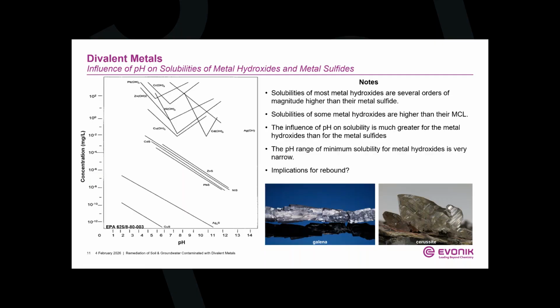So in contrast to the metal sulfides, look at the slope of the solubility curves. They're much flatter, the absolute solubilities are lower, but they're much less significantly impacted by changes in pH, particularly by acidification. So even when you get into the acidic range, the metal sulfides retain solubilities well below your MCL or other relevant remedial standards.